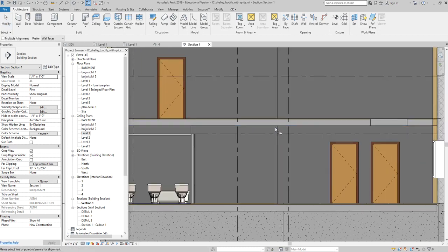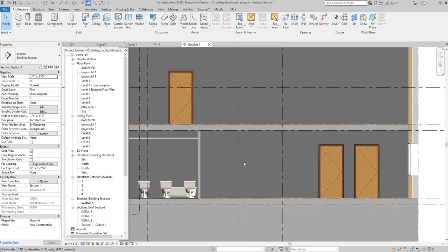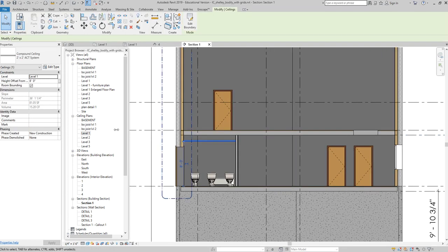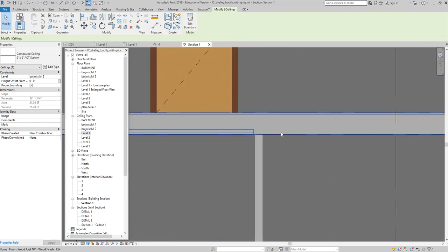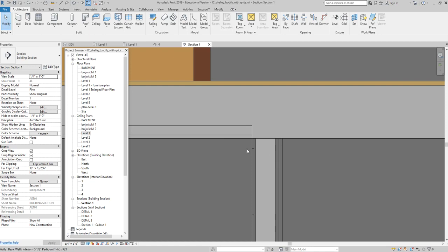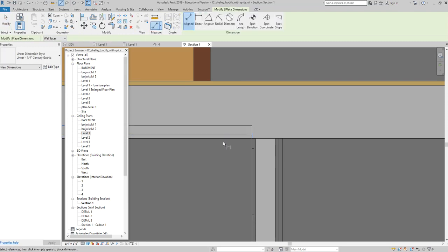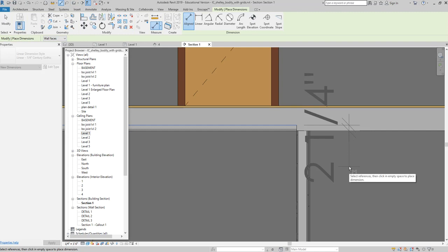Let's place this joist thing right there. There we go. Bottom of joist level 2, and we'll place this at bottom of joist level 2 with a 0 foot offset. And oh, now it's in line with it, but that ceiling has a thickness, okay? And I'm going to use my dimensions, DI, and I'm going to measure that. That's 2 1/4 inches.